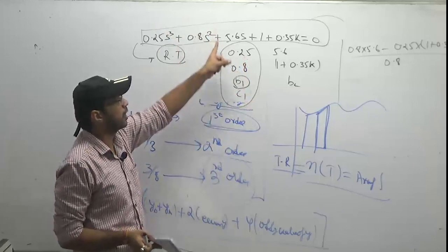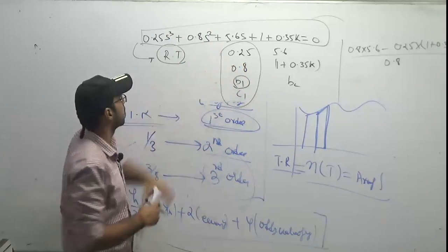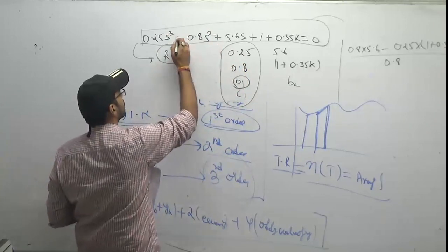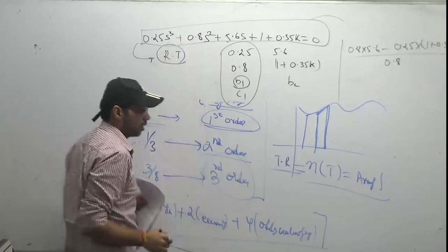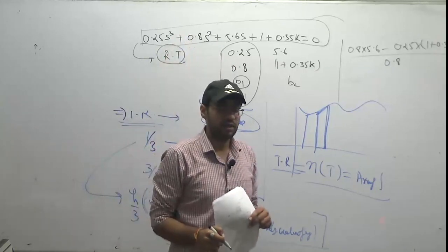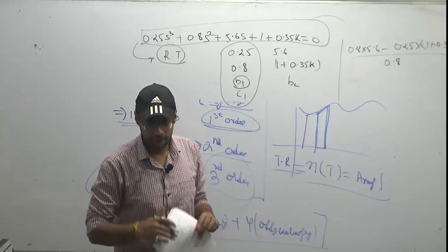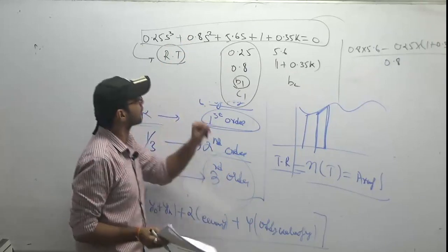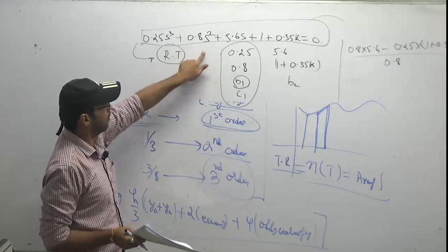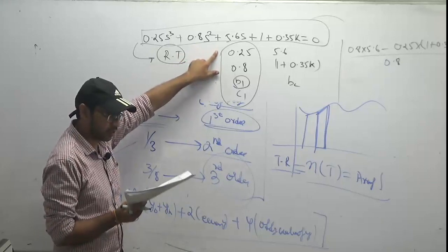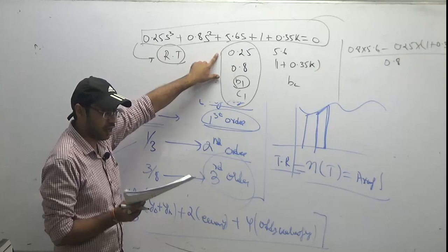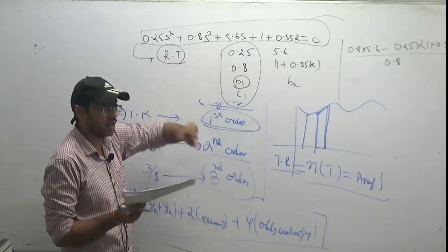If one of the components is negative, then we can say we have a root in the right half. So we can apply the Routh test to calculate the limiting value of k above which the closed loop system is unstable.